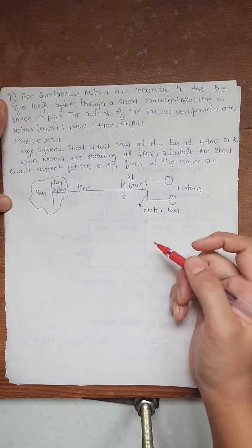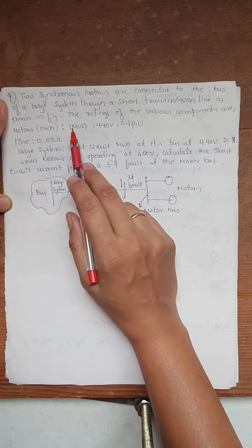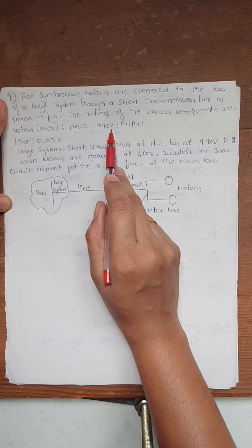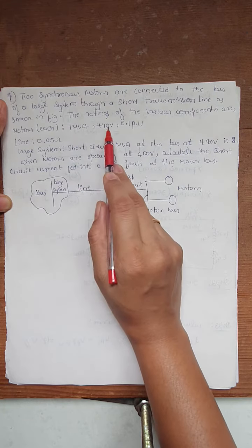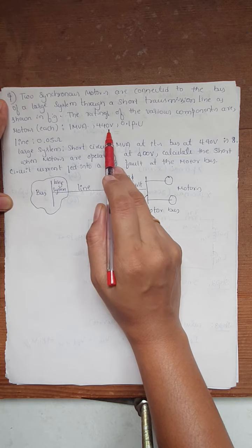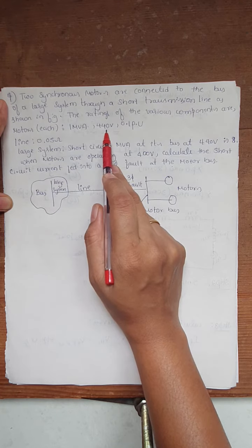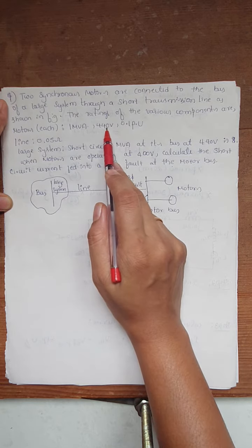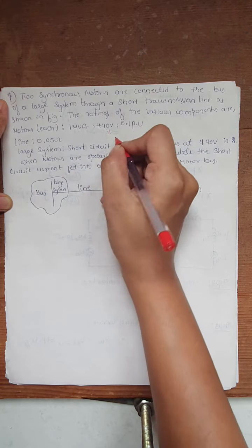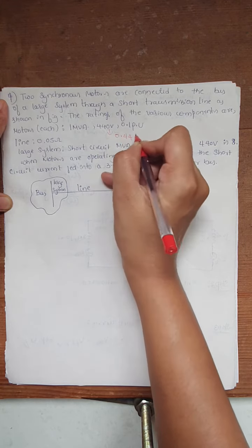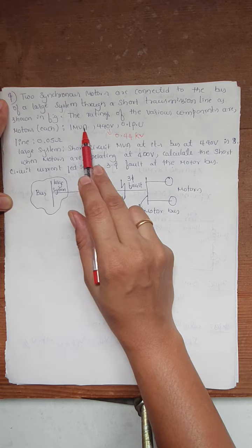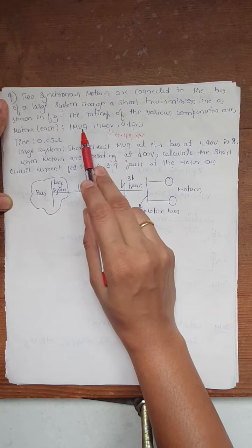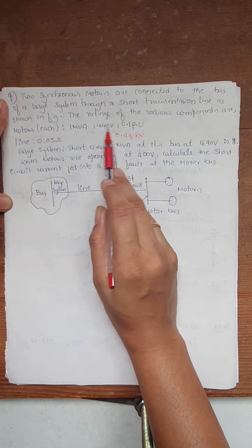One important thing you have to observe here is that the motor power is given in MVA, so the voltage should be in kilovolt, because it is expressed on a three-phase base. Before proceeding with the calculation, we can convert 440 volt into kilovolt, so I can write the motor voltage as 0.44 kilovolt. Remember, the power and the voltage both should be on a single-phase or a three-phase basis. One in three-phase and the other in single-phase cannot be considered.